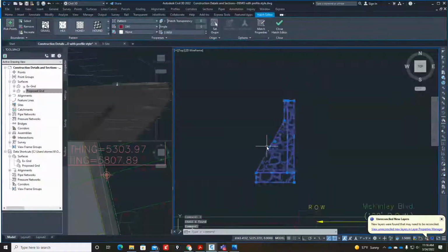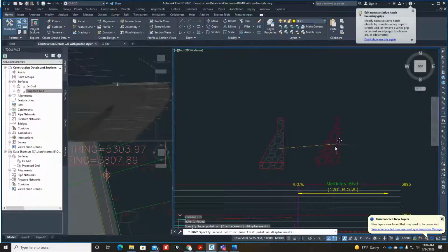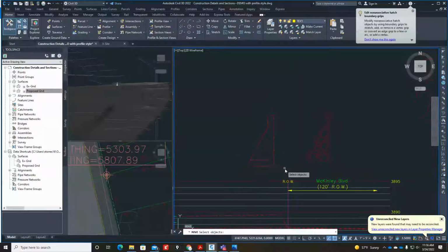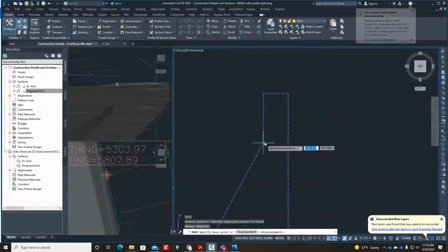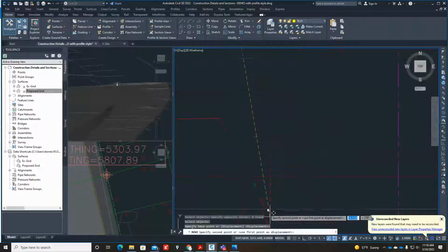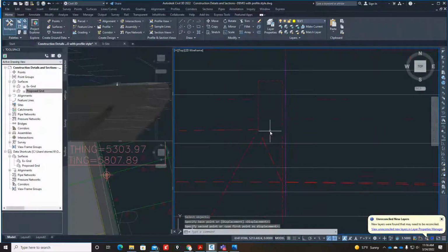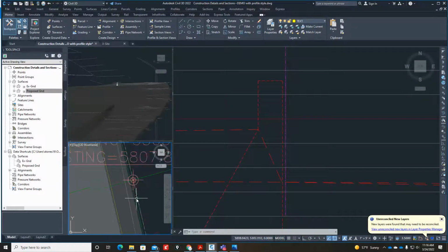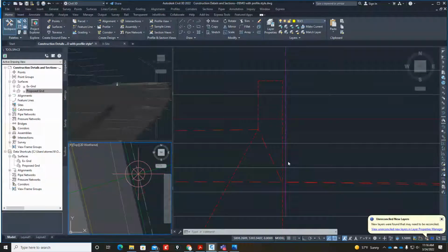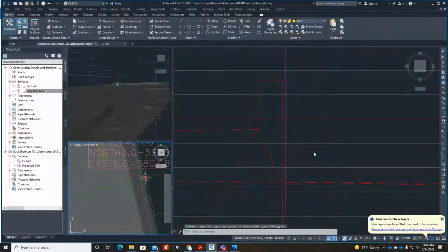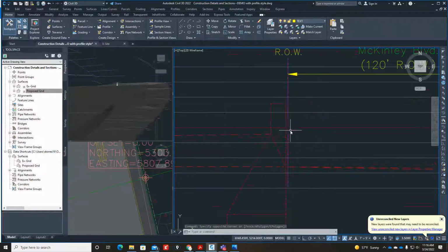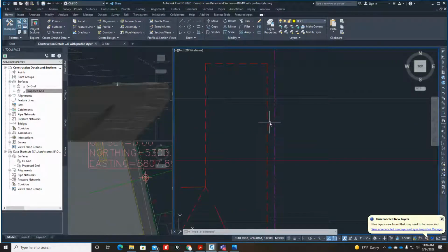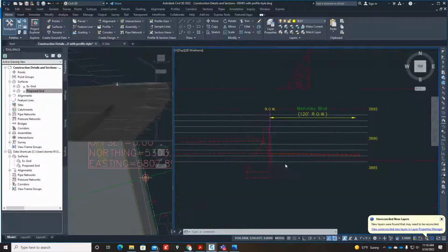I'm going to redraw the hatch pattern. So I'm going to move that guy out of the way. And then going to go ahead and place the rock wall probably from this endpoint here to probably this endpoint right there. There's a little bit of a gap in here. Let's see. And that's kind of really what's happening here. I don't necessarily agree with this too much. You usually put the rock wall right up against the property line. That's the surface here. At this point, this is such a small little detail that you can probably leave it like that. You'll be okay.